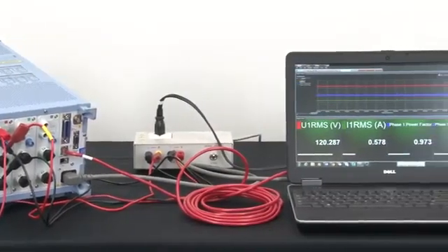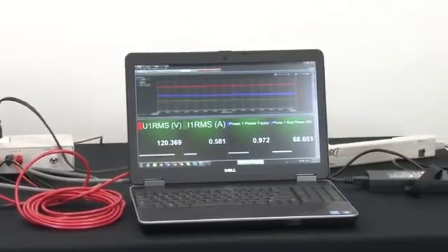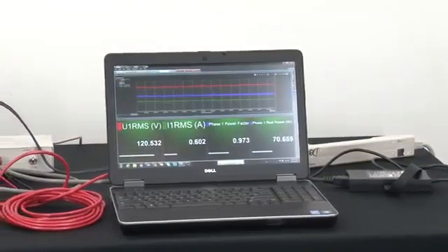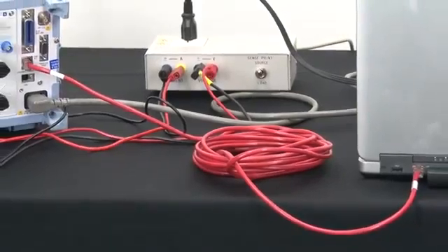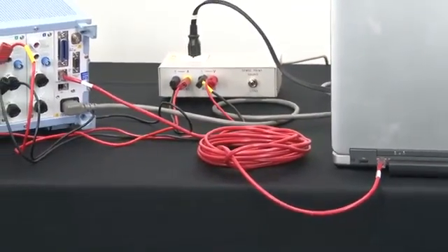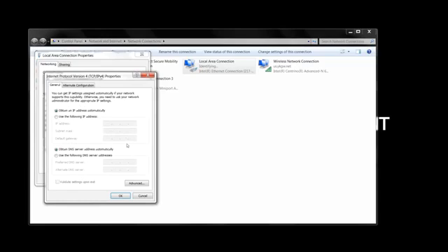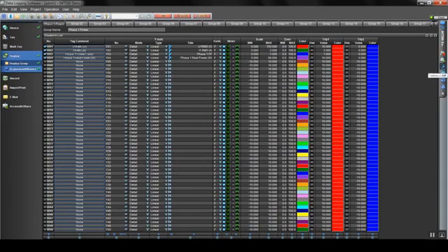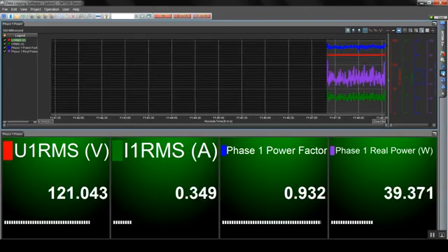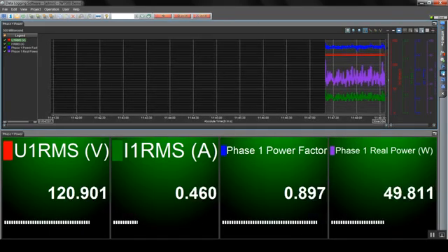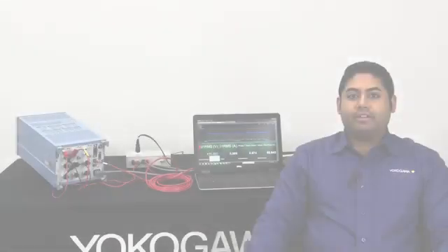We made all proper electrical connections from my load to the custom load box and the WT500 power analyzer. We established and verified communication connections from my laptop to the WT500 power analyzer using Ethernet interface. We set up and established connectivity between the power analyzer and gate WT for GA10 software, which acts as a server that communicates with the WT500 via TCP/IP. This server is needed for the GA10 to read from it. Lastly, we registered the device in the GA10 software and set up custom displays for monitoring variables from the WT500.